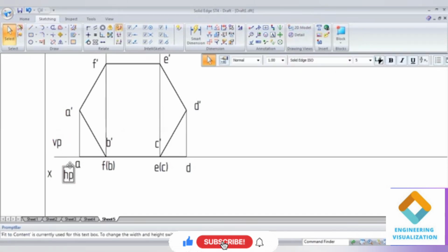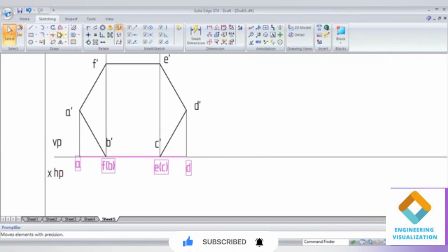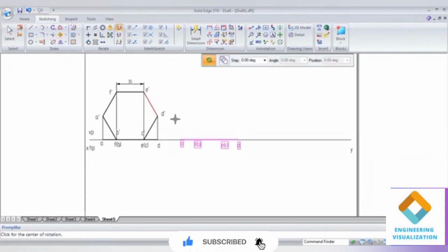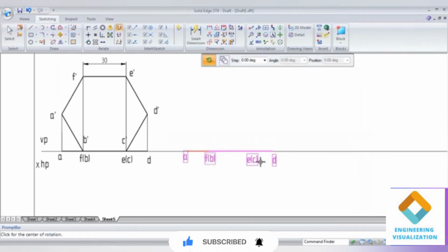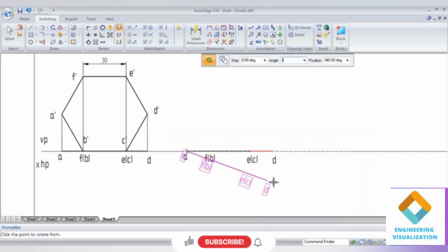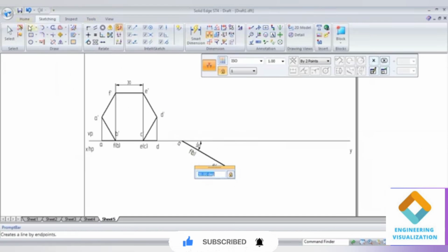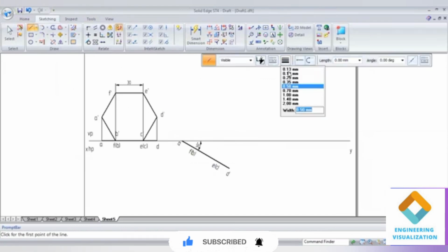Now I will select this top view. The top view line I am going to incline at an angle of 30 degree. Go to the move command, create a copy of it, and then slide along the line here. Select the two end points of the line, and give the inclination of 30 degree. So that is the inclination to VP given. Show the angle 30 degree.